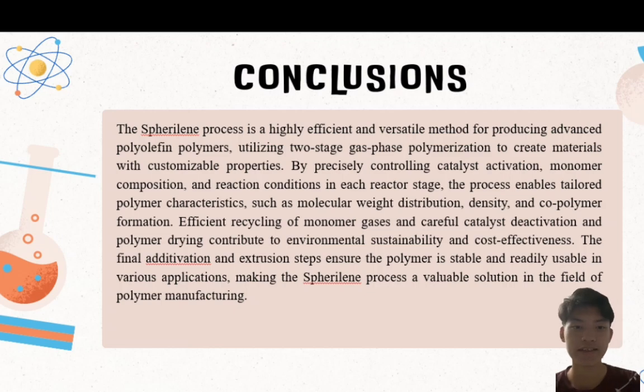Efficient recycling of monomers and gases, careful catalyst deactivation, and polymer drying contribute to environmental sustainability and cost effectiveness. The final additivation and extrusion steps ensure the polymer is stable and readily usable in various applications, making the Spherilene process a valuable solution in the field of polymer manufacturing.